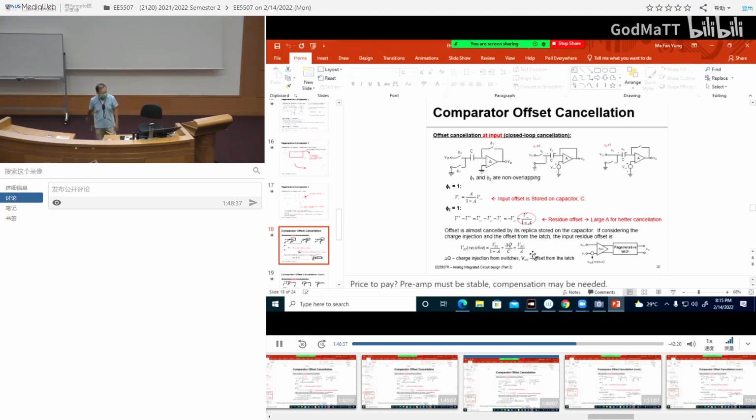So that is how you would do it using Cadence. You run a Monte Carlo, and the Monte Carlo will be many runs, because you want to have statistics. So Monte Carlo could be 100 runs, and for each run, the simulator would randomize a few parameters. So we simulate 100 runs, 200 runs, then you can see the Gaussian.